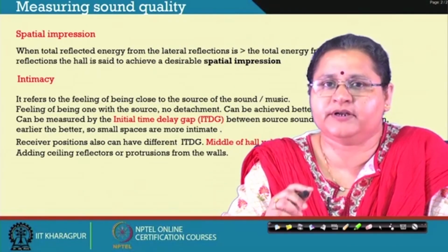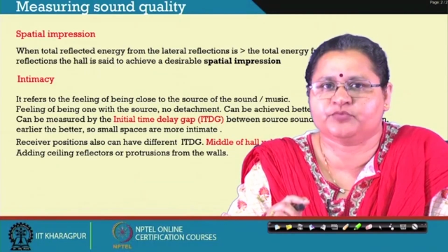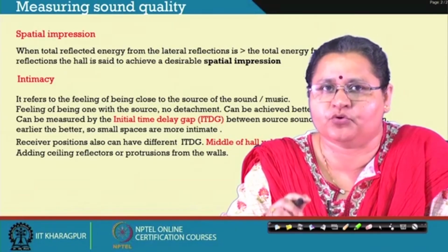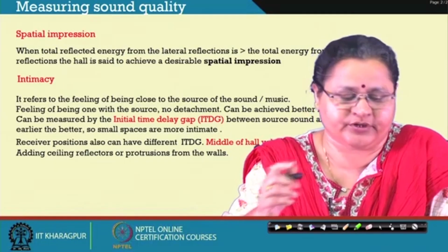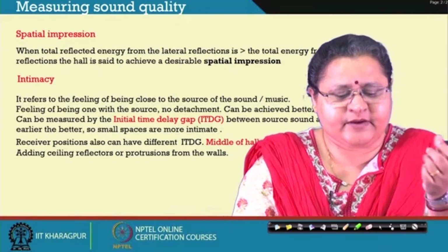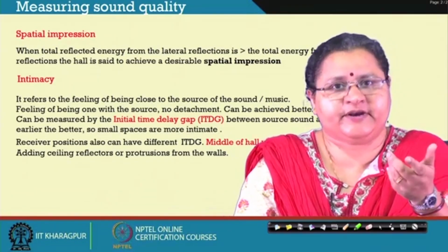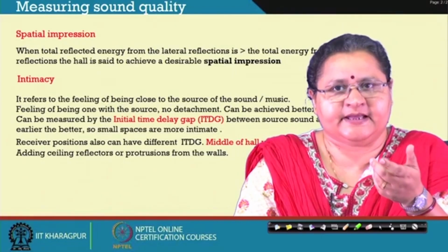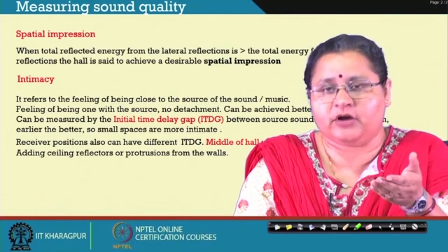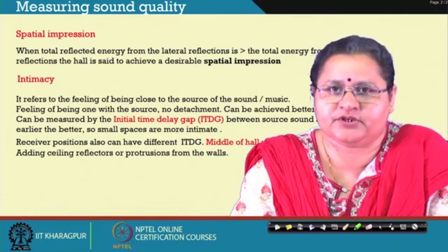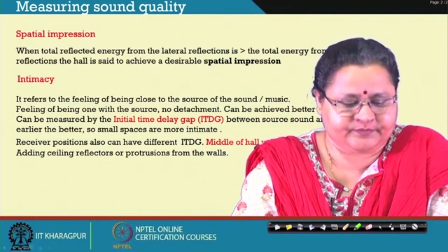So, these boundary conditions are first to be determined to achieve a good sound quality within an auditorium. The receiver position can also have different initial time delay gaps, but the middle of the hall value is suggested to be 15 to 25 milliseconds.